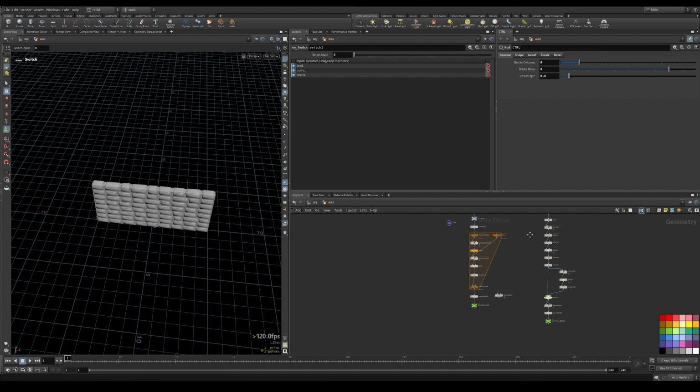And basically this concludes the second step. And if all you need is a low poly mesh, you can basically skip to the point, I will put some marker, where we will create the HDA, because from now on everything we're going to do is to create some custom remesh to add details to the brick and the grout. And also we will use some VDB to obtain a grout mesh with the holes, so it's something that you can use for RBD simulation.